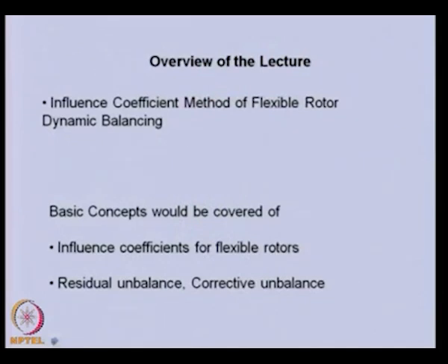The overview of the lecture is that we will describe the influence coefficient method for flexible rotor balancing, especially the dynamic balancing of the rotor. Apart from the concept of the influence coefficient for the flexible rotor, which is slightly different compared to the previous rigid rotor case we described, these are the terminologies we will be using: residual unbalance and corrective unbalance in the present analysis.